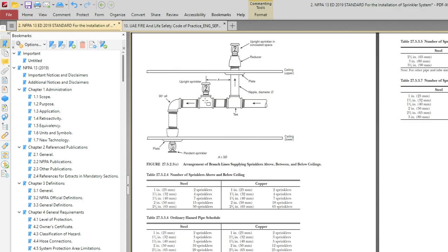See, what I'm saying is, if the distance between your false ceiling and the slab is more than 800 mm, then you will be adding another sprinkler to protect the area above the false ceiling. First we will do this calculation, then I will explain that part to you.